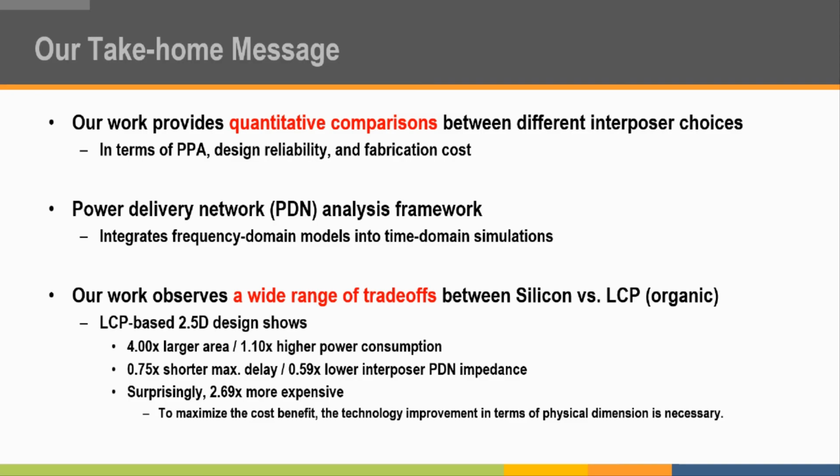To summarize our work, we conducted a quantitative comparison in terms of PPA, reliability, and cost between silicon and LCP interposer-based 2.5D ICs using commercial quality design and simulations. We developed a PDN analysis framework which integrates frequency domain models into time domain simulations. Our work observed a wide range of trade-offs between the two 2.5D designs in all aspects.